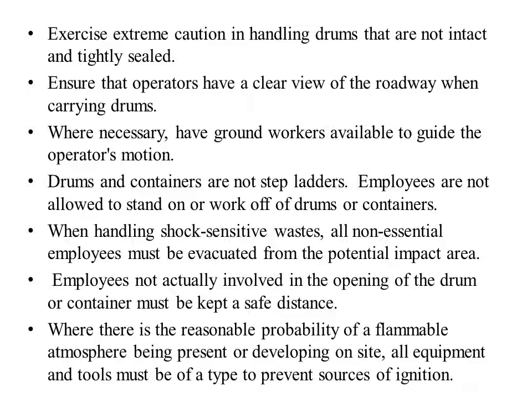And we should take extreme caution in handling drums that are not intact or which are not tightly sealed. We should ensure that the operator has a clear view of the roadway when carrying drums. That means his view should not be obstructed, whether he is carrying manually or through mechanical vehicles. And if necessary, ground workers, that means some other workers, may guide the operator's motion if needed.